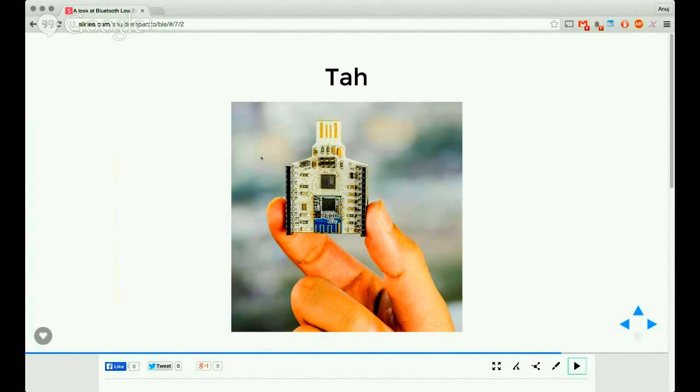If you take a look at it, it has an onboard USB, which makes wires redundant. You can directly plug it in to your USB port and start programming. It has dual inline parallel pin headers for all the analog and digital pins. The antenna is conveniently located at the very end so that it maximizes the range. In fact, it's not visible in this photo, but on the back side there are no electrical wires, which increases the range of the antenna. We tested it in a straight line, and it was almost 150 feet, which is excellent.